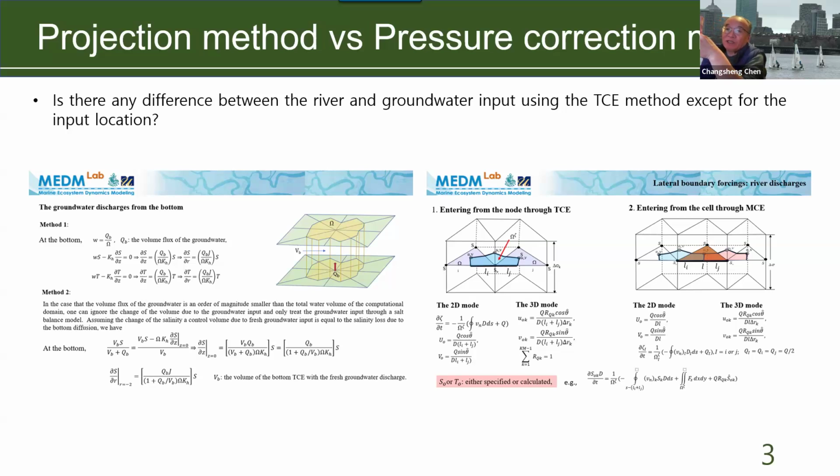It can build a pressure gradient, and the pressure gradient can be unusually high. It can cause buoyancy circulation locally, particularly for low resolution, right? But with the momentum method, because they push and dump the water in there quickly, they don't build the pressure gradient there. So when the freshwater flux is smaller, you had better use the momentum method.